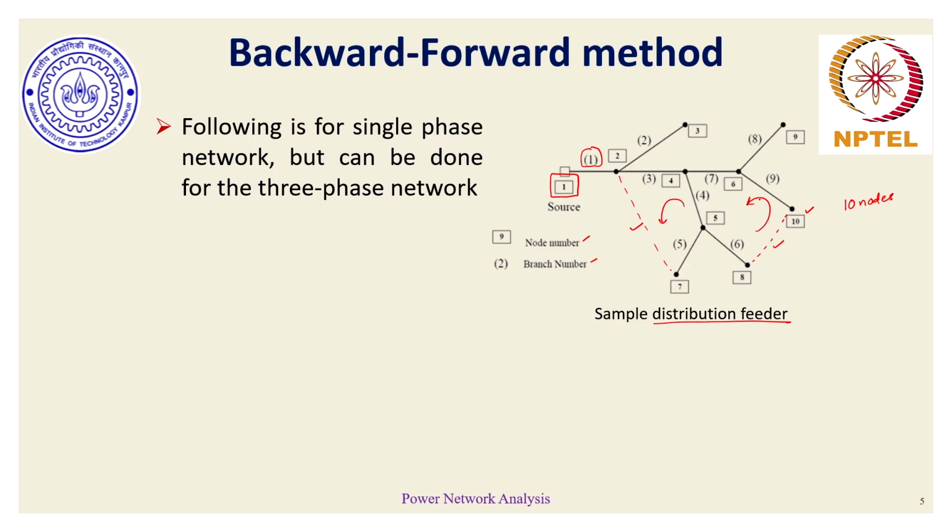In case one path is away, the distribution loads will still have alternative routes to get their power feed from. In a typical radial structure, if one branch is disturbed or experiences a fault because of which the line becomes non-operational, the entire network loads will have no other path to get their source supply from. That's the essence behind a radial network.